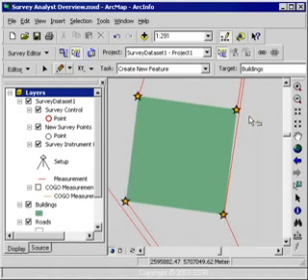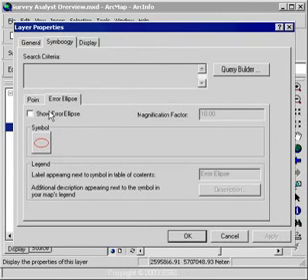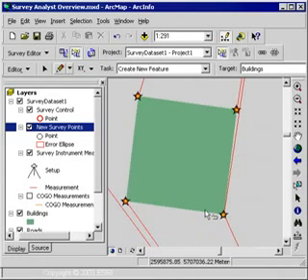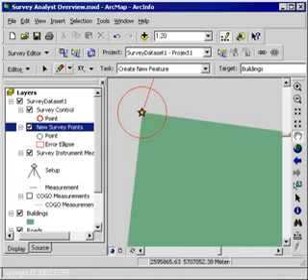I'm going to close the Survey Explorer for a moment and examine the properties of those survey points. One of the things you can do is turn on the error ellipse and display the accuracy of that point. In this case, I'm going to magnify the error ellipse information by 10. The reason I'm doing that is so you can actually see it. At this scale, you can't see it because the survey point is very accurate, even if I magnify it 10 times. Now you see the error ellipse represented on the screen.